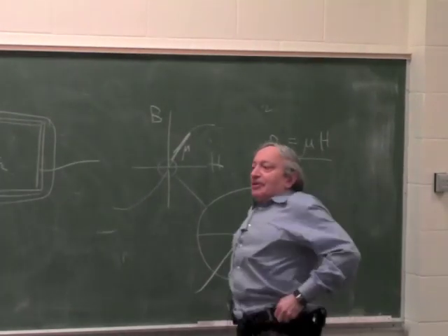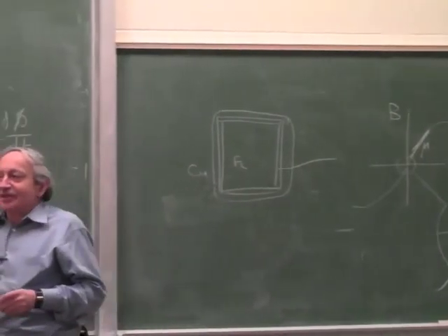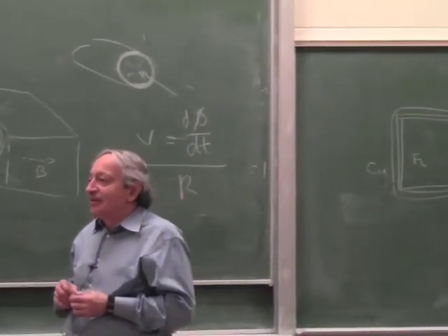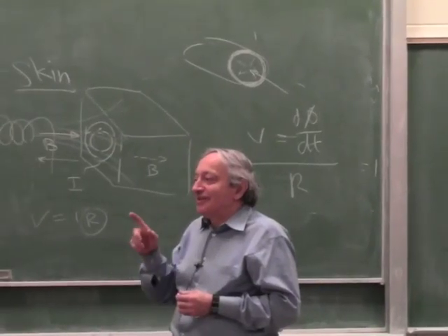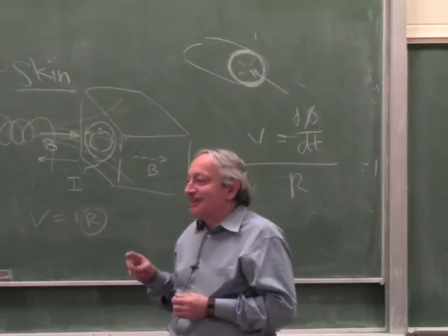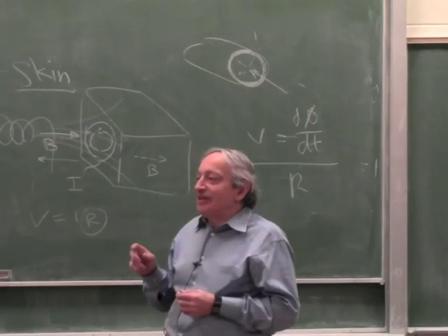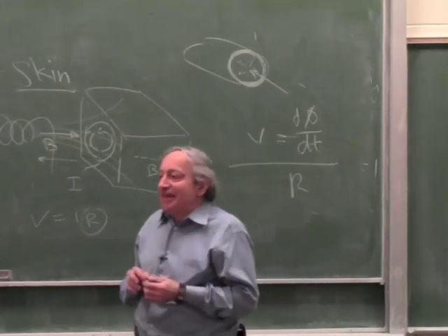So you have to think about how magnetism is formed in steel. Okay, yes? You need a certain amount of magnetic moments to line up. To line up what? In an orientation to your magnetizing force. Yeah, but what are you lining up? You are very close, but... The dipole? Or magnetic moments. You basically line up the domains.